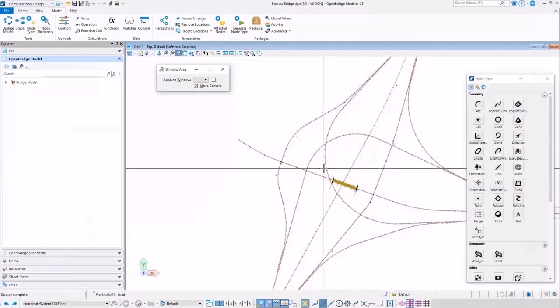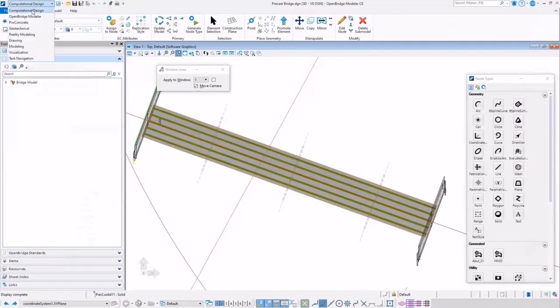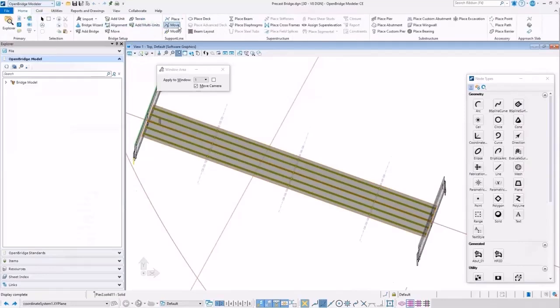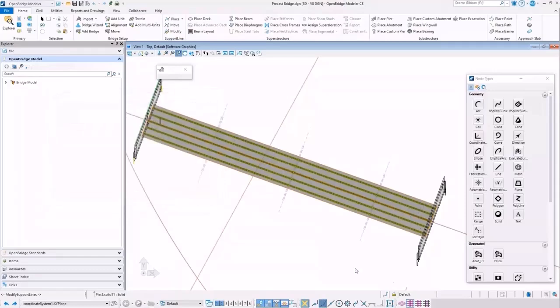So, and then on top of that, I can try to enlarge this now. Okay, so for example, what happens if I fix all of these, I've got the abutment that I want, but then they say, oh, we need to make the bridge longer or shorter. So then just do it, because the GC element that we're placing is not just a GC element, it's actually, as Francois mentioned, a civil element, a bridge element per se. So for example, here, I'm just changing, and this abutment will just move. This GC abutment is actually a bridge element itself, so it will update the bridge accordingly. If I need to map new variables or just modify variables, I just go in and change it.